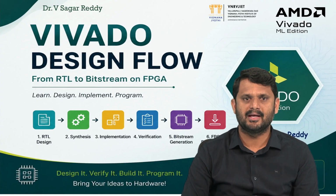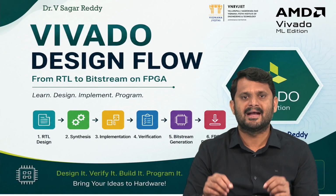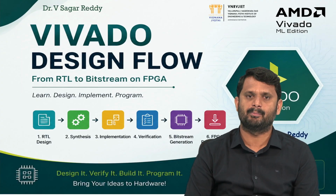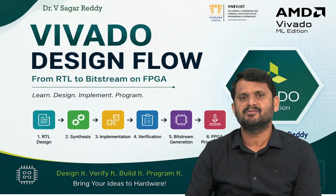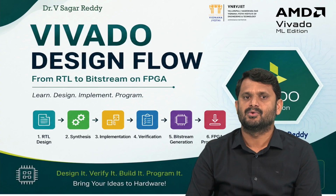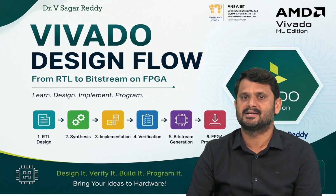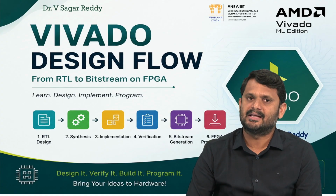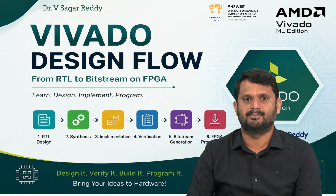In today's video, I'll explain the complete AMD Vivado design flow. So we'll start from the Vivado home screen and understand each step involved in developing an FPGA design using Vivado. By the end of this video, you will have a clear understanding of the entire workflow. So from creating a new project, adding design sources and constraints, running a simulation, synthesis, implementation, and timing analysis. Finally, we generate the bitstream.